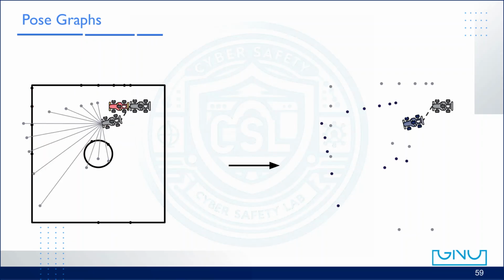As we continue, the map becomes increasingly distorted. LiDAR keeps observing the correct environment. But because the odometry is wrong, the map pulls apart and bends in unnatural ways. We'll have the right measurements from the LiDAR scanner. Mostly, we're going to ignore the noise on scans here. Our mapping algorithm will mistakenly put the points in the wrong position using the wrong odometry.